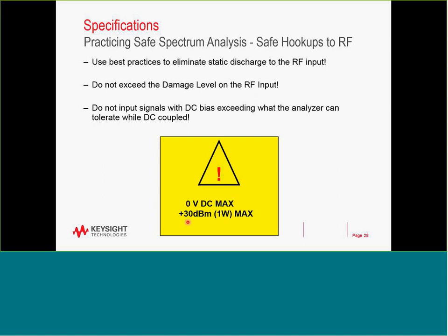And you have to ask yourself, when I'm testing my transmitter, if the transmitter doesn't behave properly, what can be the maximum power? If it starts to oscillate, can I get more than what I think it will generate when it's working? So I would say a good rule of thumb is to put some attenuation, put an external pad in first, verify what you have, and then lower the pad value.